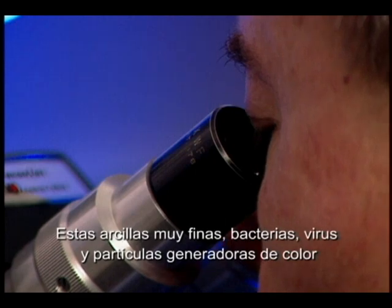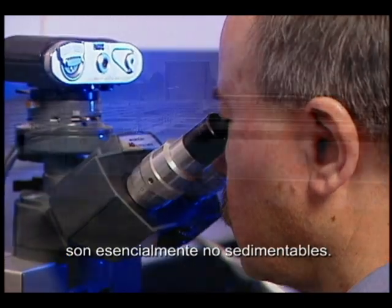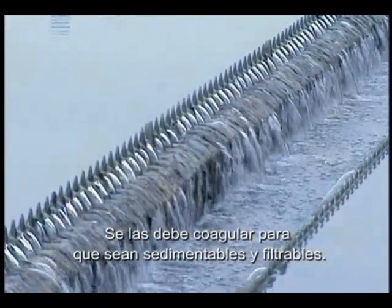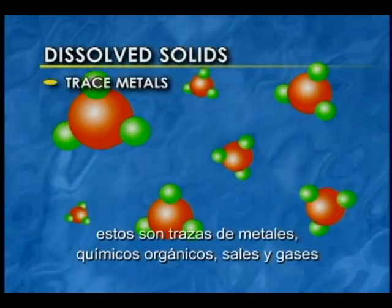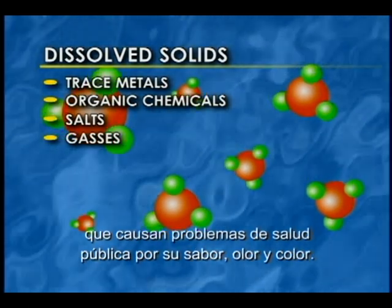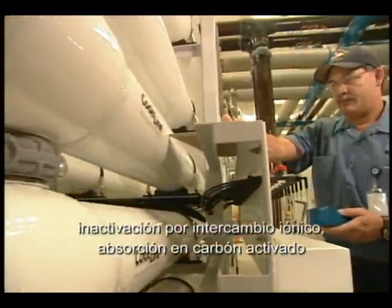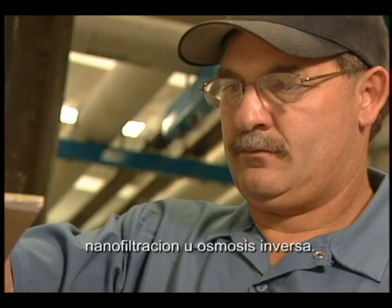These very fine clays, bacteria, viruses, and color-causing particles are essentially non-settlable. Unaided, they would take days or even months to settle out. They must be coagulated to become settleable and filterable. Dissolved solids are the size of a molecule. These trace metals, organic chemicals, salts, and gases cause public health, taste, odor, and color problems. Some can be removed by chemical coagulation. Others may require additional treatment, such as ion exchange, sorption on activated carbon, nanofiltration, or reverse osmosis.